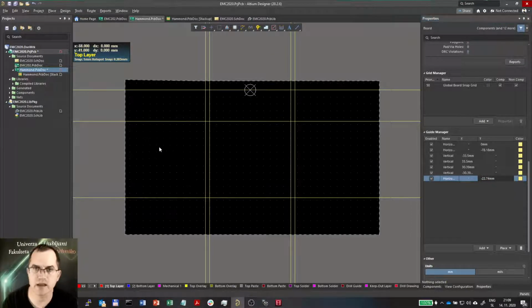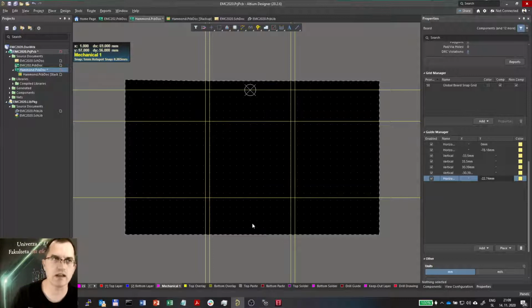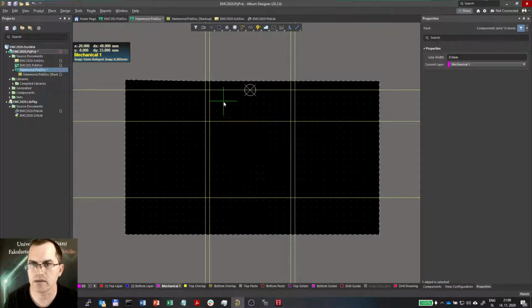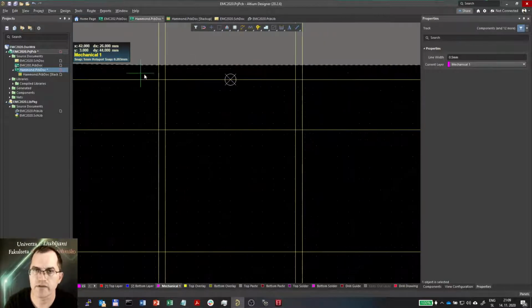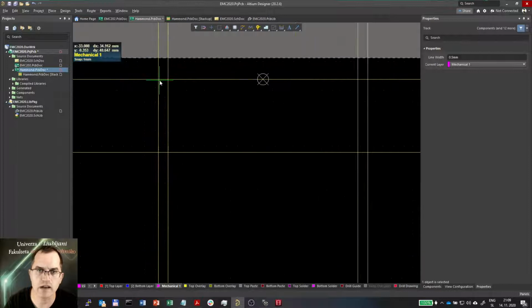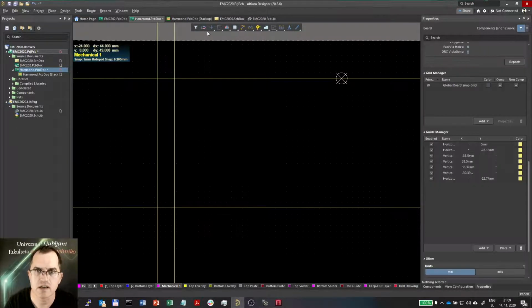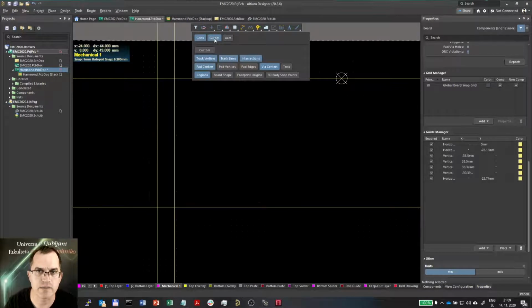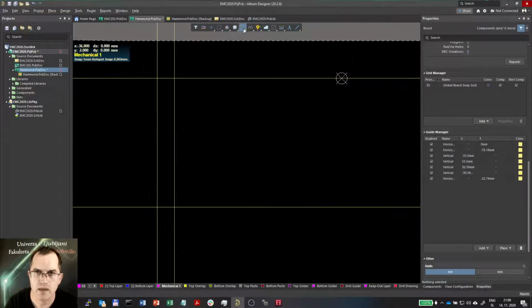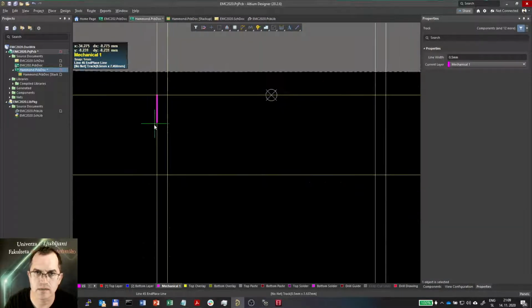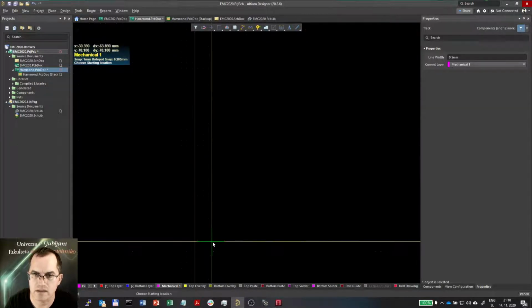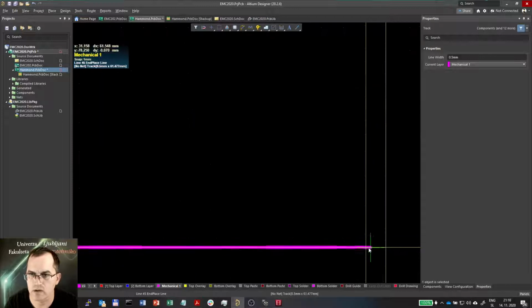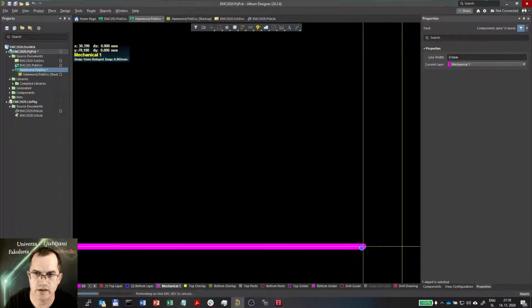Okay, now I'll draw some lines. I will go to the Mechanical 1 layer, which is used for defining the PCB border. I would use line width of 0.5 millimeter so that I can see it easily. And first I will place this here. Now I would like to snap to these guides, so I will click here and I'll use the snap to guide. Okay, I will now place this line. That was quite easy. Going down, placing that one as well. According to the guides, now it's very easy to place it accurately.